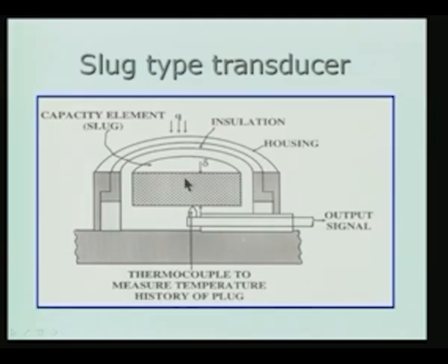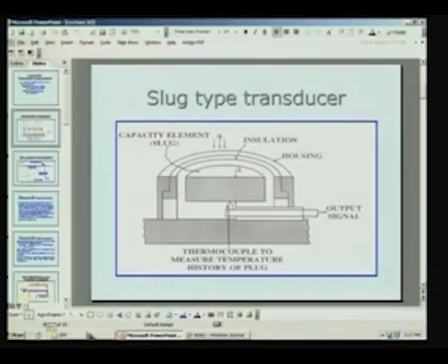This must be equal to the rate of change of the internal energy of the slug, which can be determined from the mass, specific heat, and the temperature rise product. So, let me just do a simple analysis by going to the board and explain how we are going to account for the heat loss. So, we have the slug, I am showing it as a rectangle, actually it is a circular cylindrical specimen.